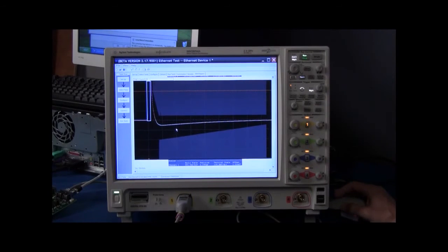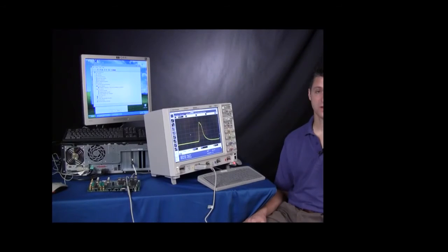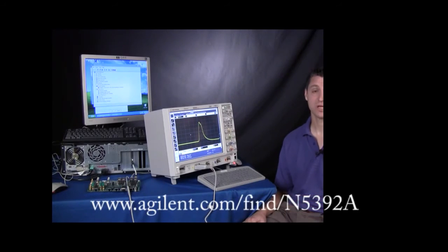And that's how we resolve our Ethernet application link pulse issue. So in this video, we showed you where we had an issue with a customer DUT with an inconsistent link pulse. We also showed you how to set up the oscilloscope as a link partner so that we could run our Ethernet application. Please check out our website below, and thank you for watching this video.